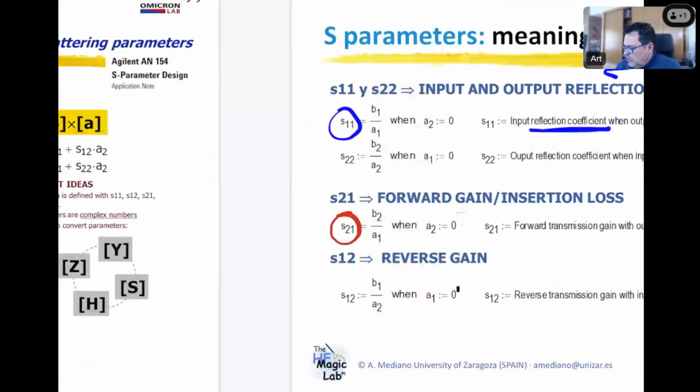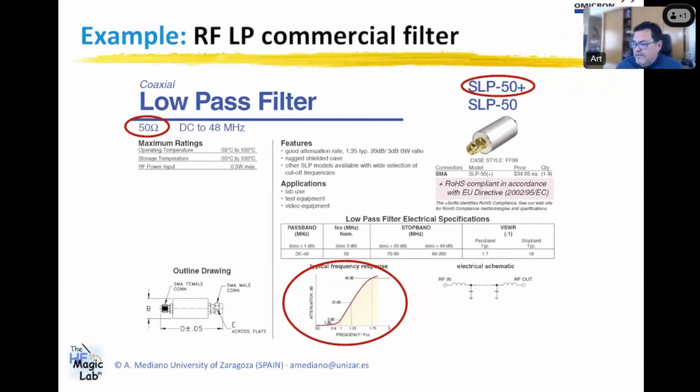So this is what we will try to explain with some demos, and we will be using the Bode 450, the instrument from Omicron that is able to reach 450 megahertz. And to introduce the S parameters, we will start using a commercial filter. So consider, for example, that you are interested in this filter. This is a typical filter for radio frequency applications, wireless communications, or perhaps medical applications, things like that, where designers are working with known terminal impedances.